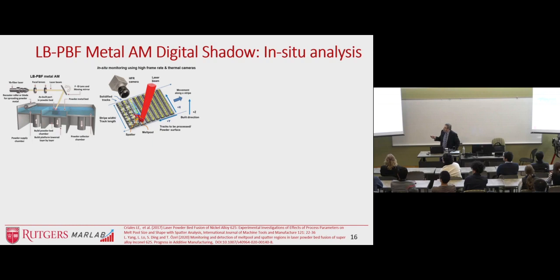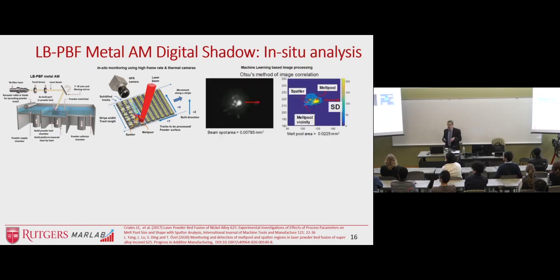And then the process parameters there are essentially scan speed, hatch distance between the two tracks, as well as the stripe width. And obviously, this is local thermal processing, and it's going to result in some kind of anomalies you can call, and as a result, defects.